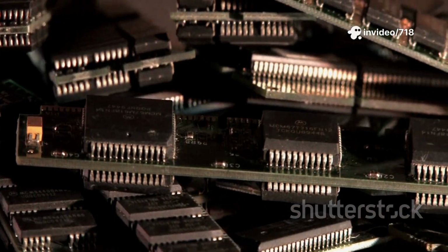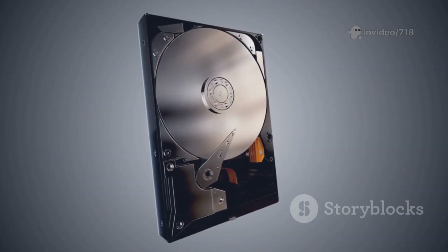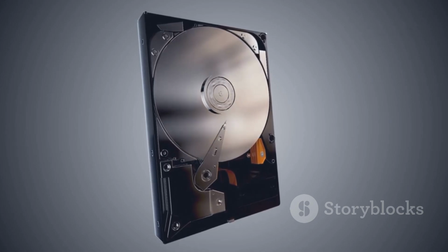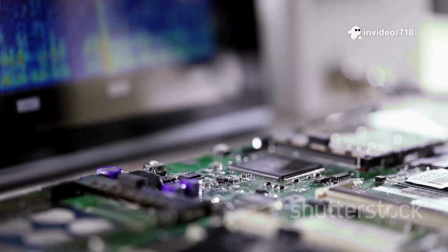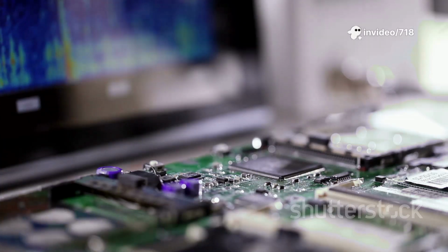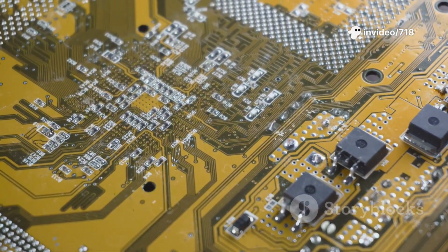This brings us back full circle to the concept of refreshing. The destructive read process explains why even accessing data helps to refresh it. But what about the data that isn't being actively used? What about the cells that are just sitting there, holding information while you're busy working with a different part of the memory? Those cells are still leaking charge.